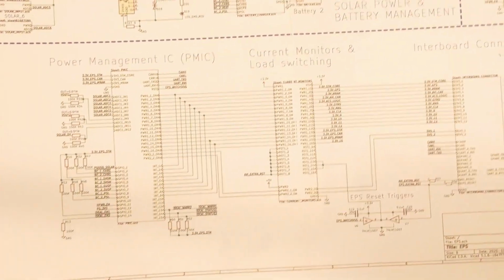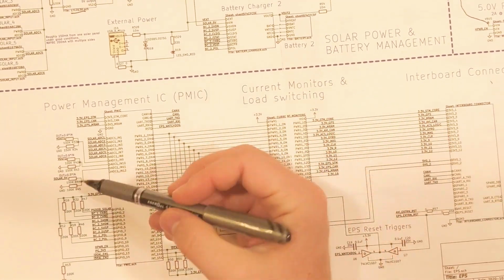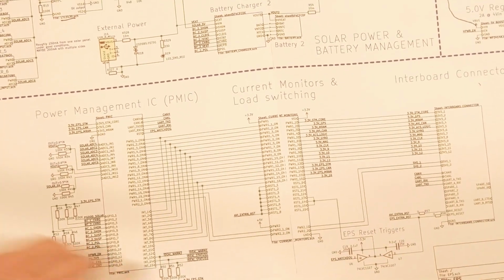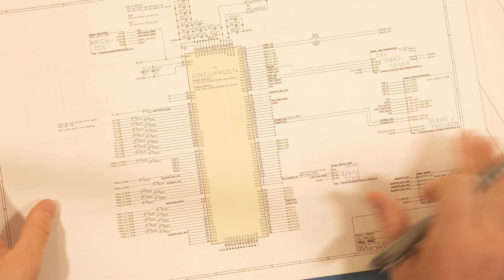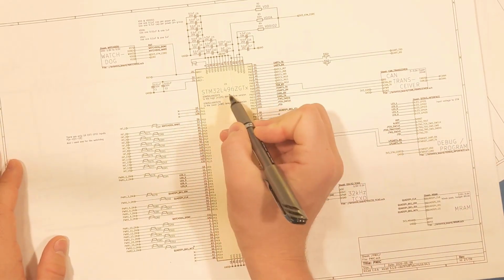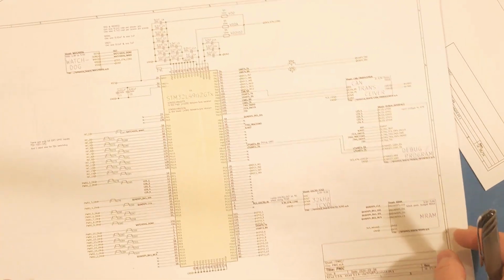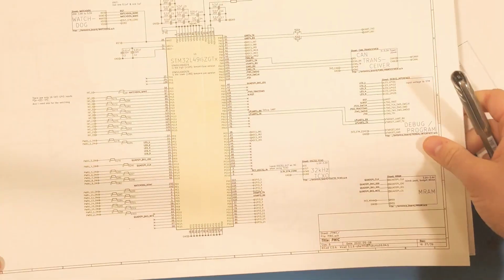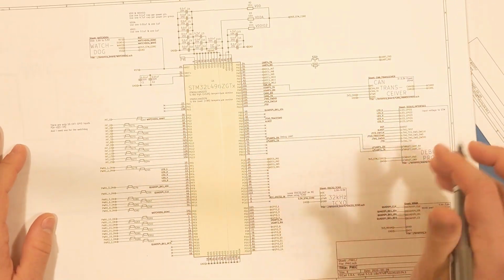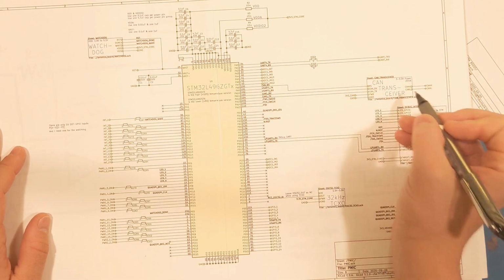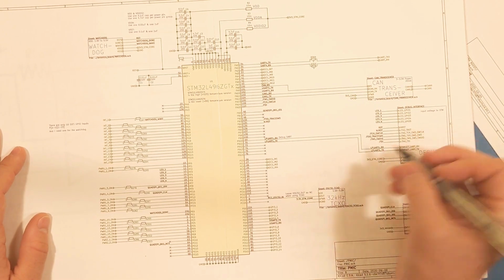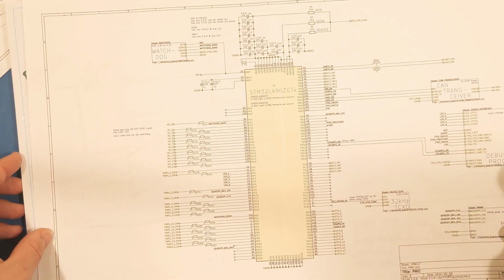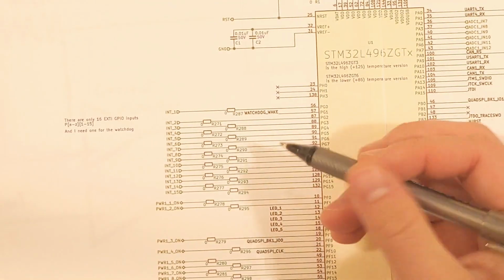Moving down to the bottom half of this board, the other big schematic that I haven't shown you is the power management IC. I said it was similar to the avionics board, and it is. If you look back at my other videos, you'll see that I'm also using an STM32L4, and in the other videos it had a whole bunch of other sensors that are not here, and that's for good reason because this is just for power management. All I need is the CAN transceiver, which is the same, the debug port ends up being the same, the 32 kilohertz clock, and I still have the same MRAM memory. Otherwise, I have just a whole bunch of GPIOs.